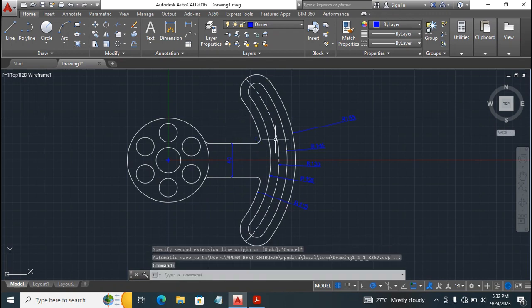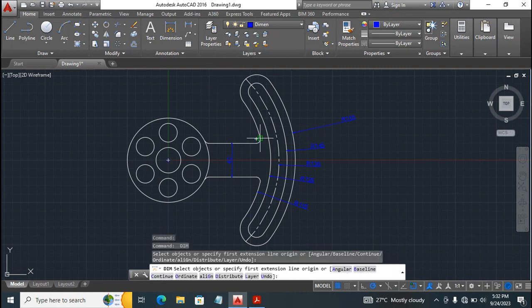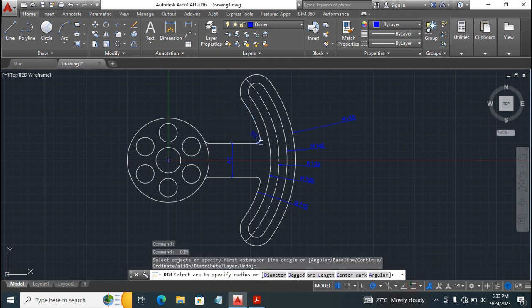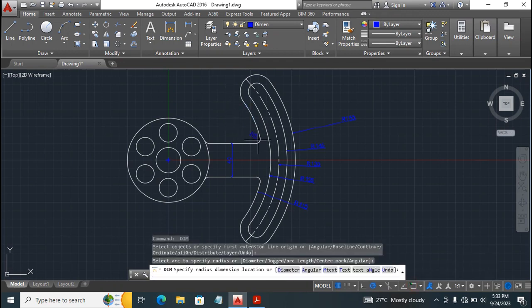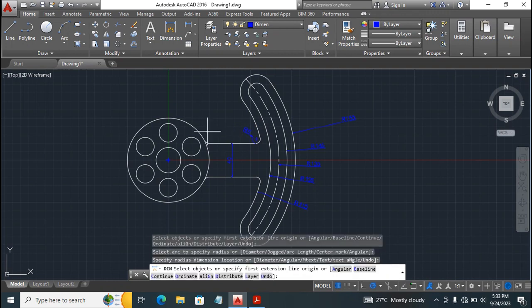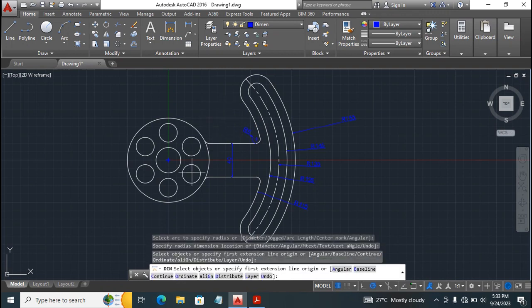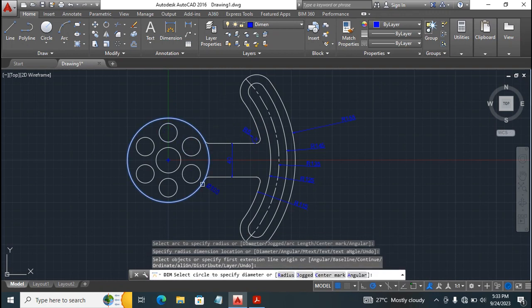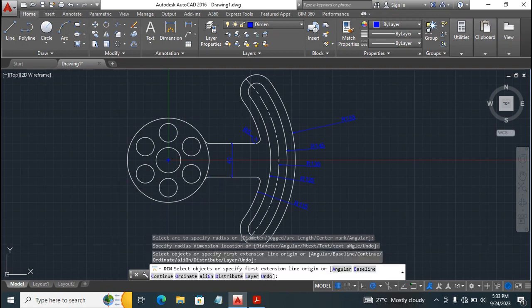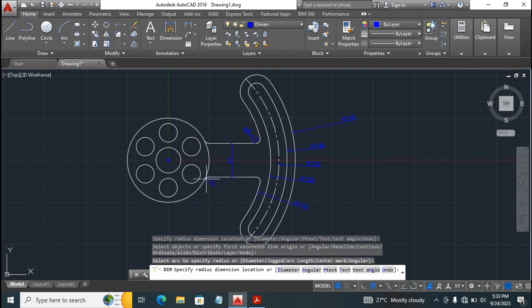That didn't go well. Escape, spacebar to enter the previous command. Deselect the object snap option. All right, yeah, correct. The fillet radius here is 5. Okay, do the same here. 5.